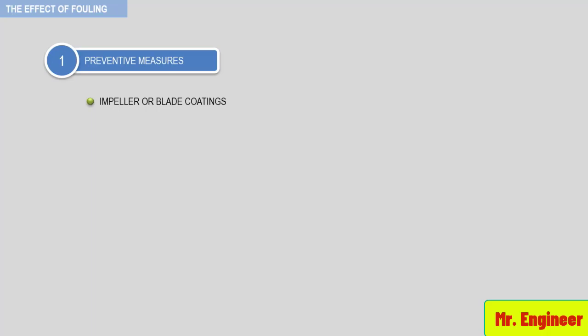In my professional experience, this has met with mixed results. There has been, however, success with coating impellers with Teflon-based material in ethylene-cracked gas services. So, for this last measure, I recommend that you talk with your process designer and ask your compressor vendor for additional information.